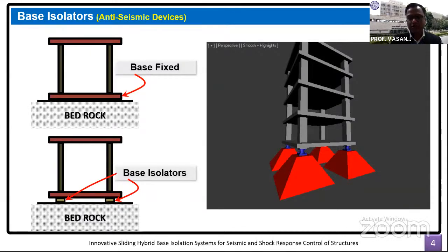The lower modes are eliminated from the superstructure. So thereby the base shear in the columns or the lateral load resisting elements reduces quite substantially. So all this theoretical background is known to us. What I'm going to present today is how it is realized in real life projects.